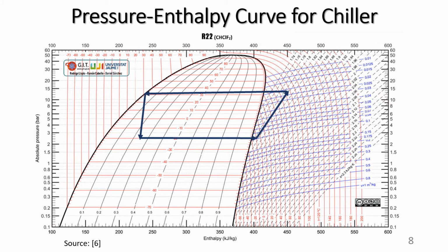During the experiment, pressure was recorded for each run and the enthalpy was calculated using the Aspen Properties database. The R22 in this process starts as a saturated liquid. For the first part of our cycle, R22 goes through an expansion valve. This expansion valve will drop the pressure of the refrigerant in a nearly isenthalpic process. R22 will now become a saturated liquid-vapor mix.